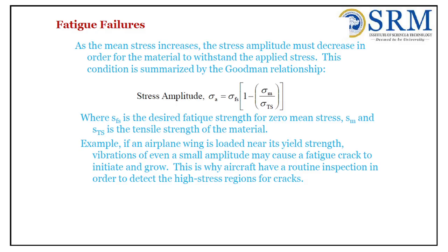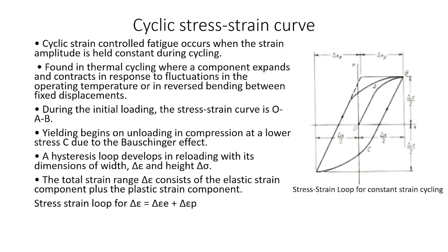Right. So in fatigue failures, as the mean stress increases, the stress amplitude must decrease in order for the material to withstand the applied stress. This is summarized by Goodman's relationship, which we have discussed in the previous slide.